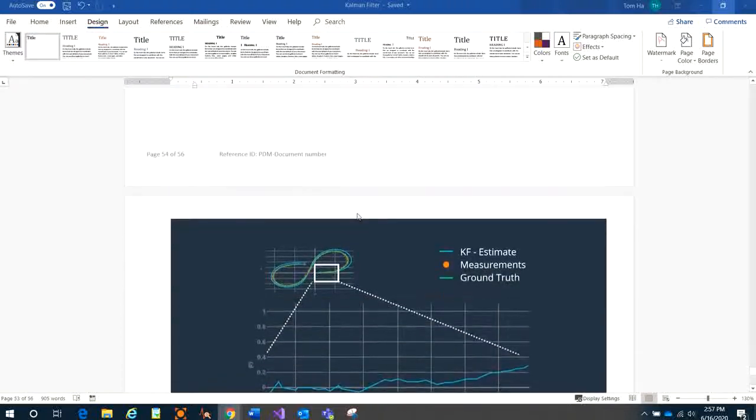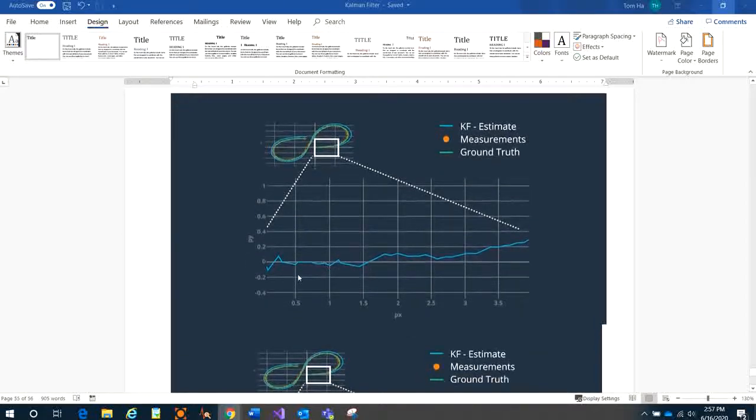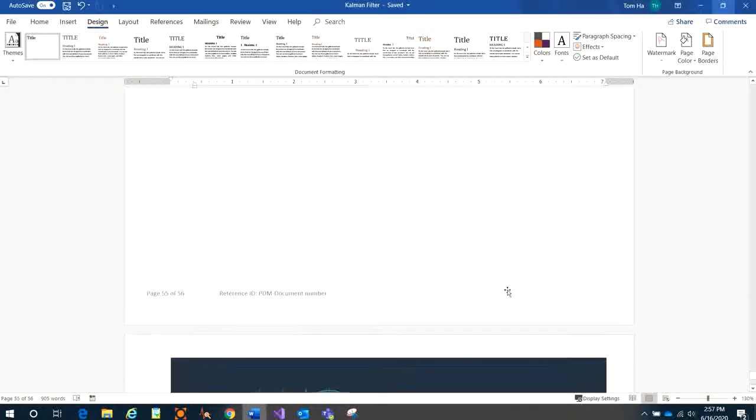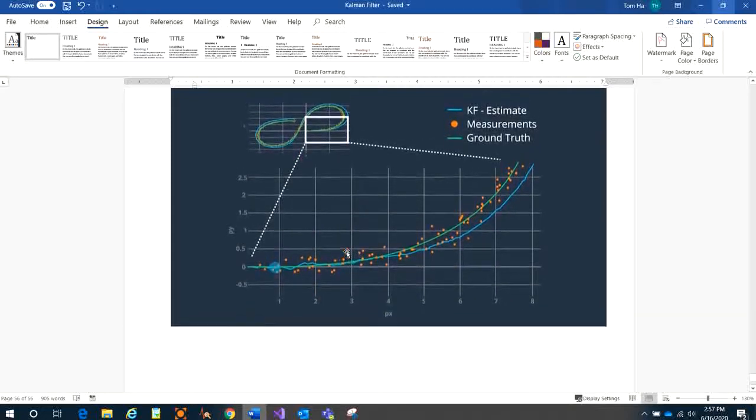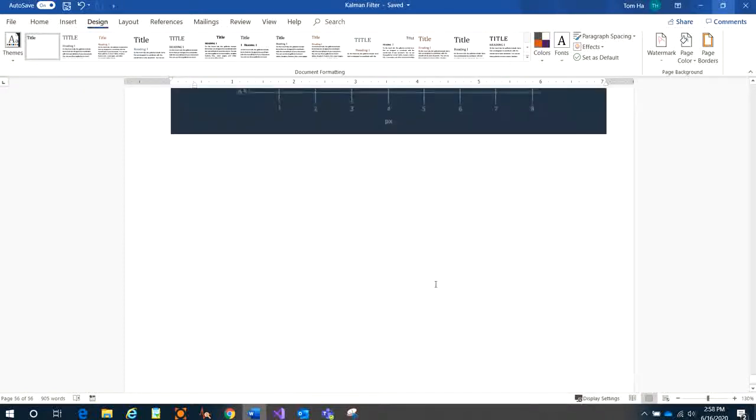The second thing, look closely at this small part. The Kalman filter compared to the laser data and the real path is really linear, straightforward, right? So it's very close, it's really good. But when the pedestrian tries to go along a curve or circle, the Kalman filter does something wrong, because we apply the standard Kalman filter. This is for linear motion, going straightforward. It's not applicable to circular motion. So what happens in this case, and how do we solve this problem?